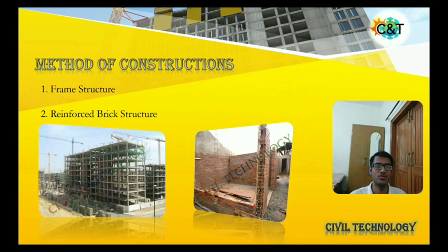If your house or location comes in areas where natural activities happen often, like major earthquakes coming within a short duration of time, or cyclonic effects happening often, then I suggest you go with the frame structure method, because it is very good at resisting the lateral forces created by natural effects like earthquakes, cyclonic activities, or heavy wind.